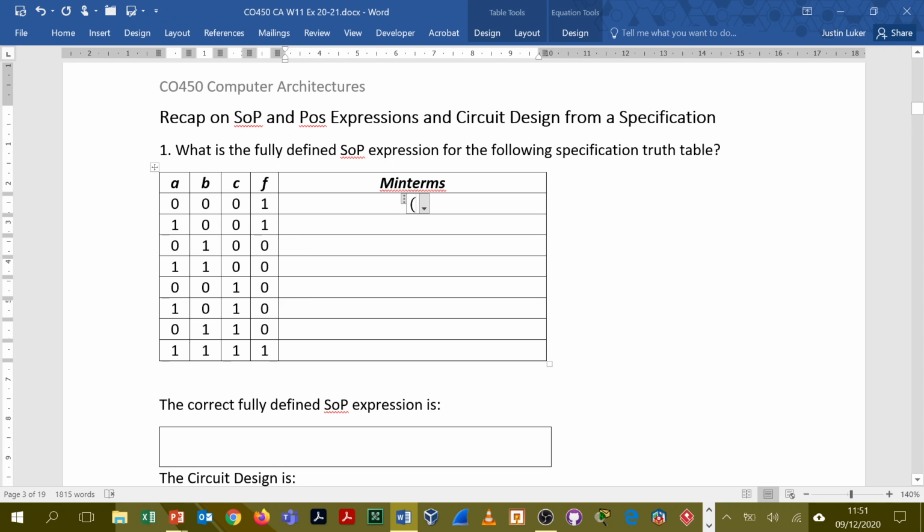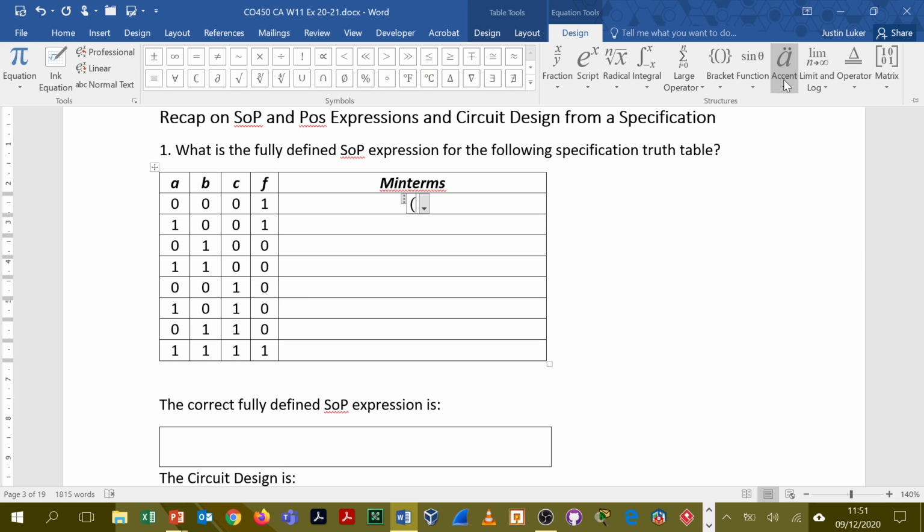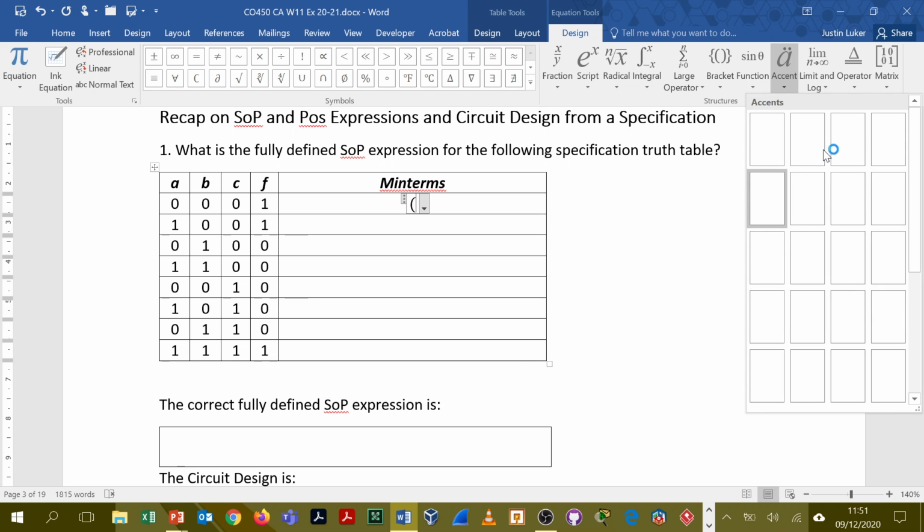So in terms of sum of products, when you have all 0s like that, and we're looking for 1s, these are not what we're looking for. So it's not A, not B, and not C in this case, because they are 0s. So it's going to have to be that with AND, because in sum of products it's ANDs first level and then ORs the second level. So let's create that. I'm going to need some NOTs here to add in.